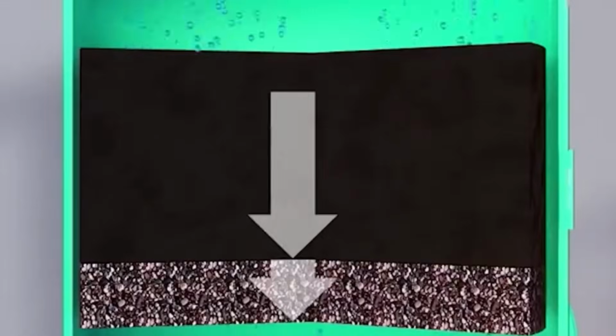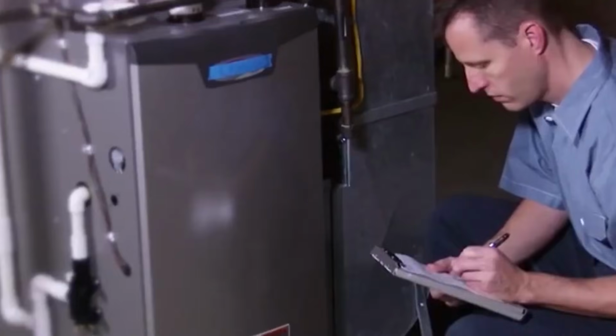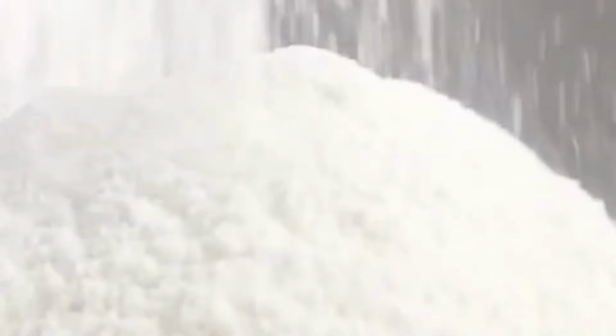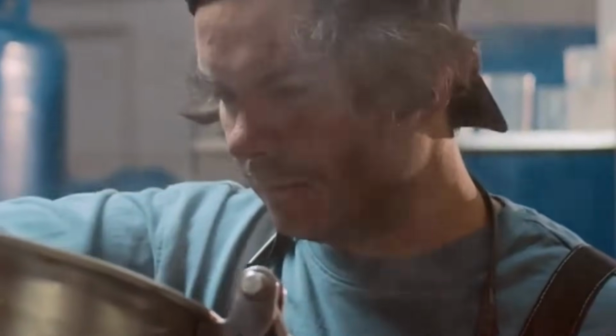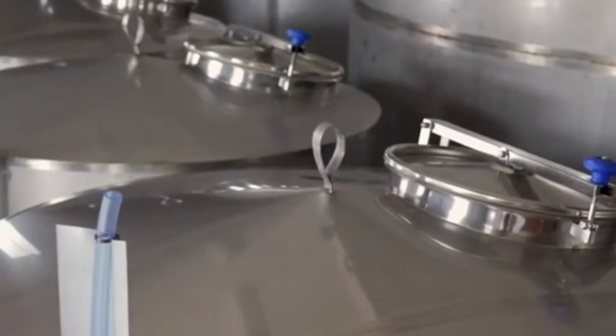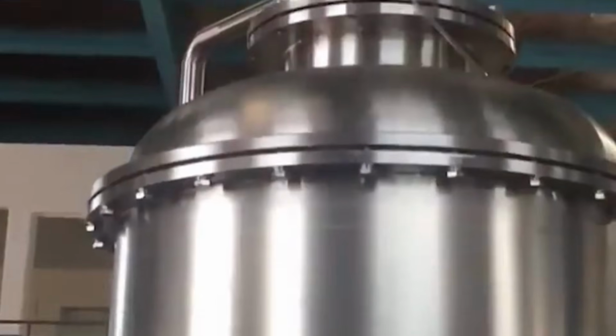Capping follows immediately. For bottles, caps are sorted and oriented using centrifugal feeders and fed into a rotary capper. Each cap is pressed onto the bottle and secured using torque-regulated chucks. Sensors verify cap presence and alignment.